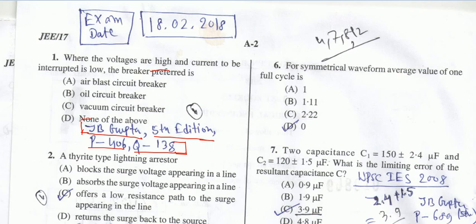The correct answer of this question will be vacuum circuit breaker. And now come to the point why. The arc extinction phenomenon in the vacuum circuit breaker is related to a great extent to the material of the contact, the shape of the contact, and the contact geometry too. If we use more than the higher rating, then what will happen? The vapor does not condense at the proper geometry, and it will not return to the original position. That means it should be used up to a 33 kV circuit breaker.